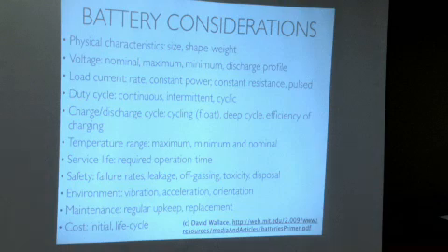Whereas with a solar panel installation or wind power, if you think about it, you don't need a really high current quickly. You need a steady current for a long period of time. So a car battery's chemistry is not made to provide that type of power. If you try to use a car battery, you're going to kill it really fast because you're discharging it too much. And all batteries have some lower limit of discharge, and you can't discharge any lower.